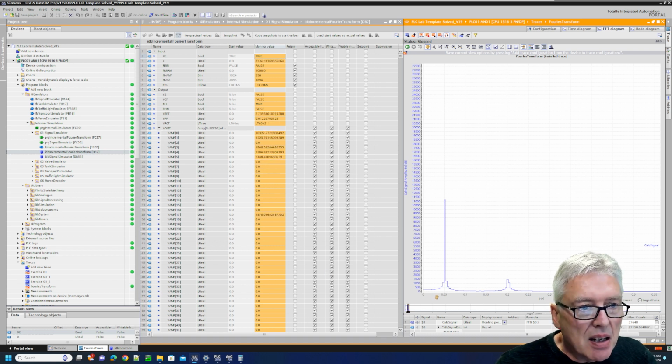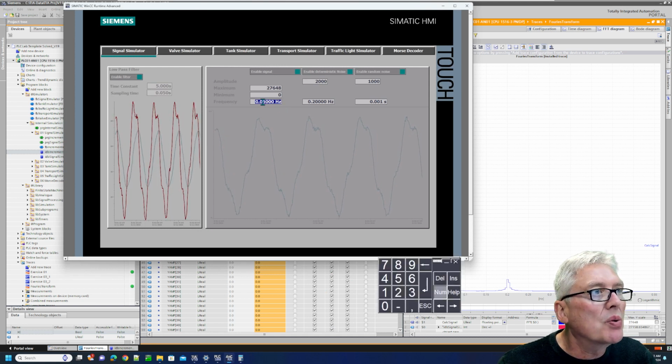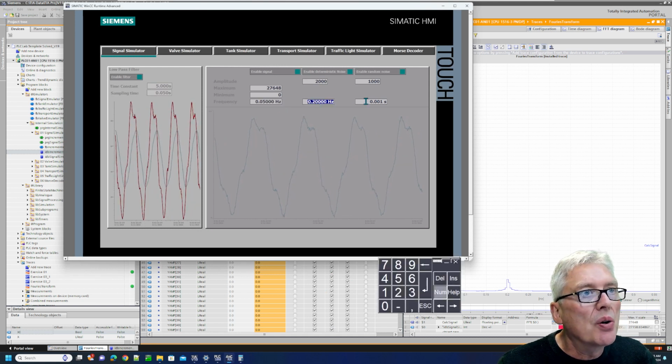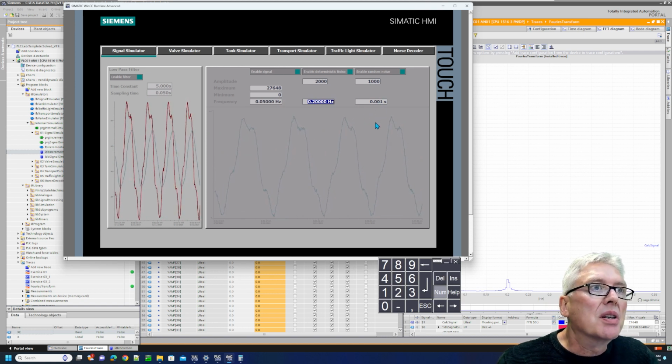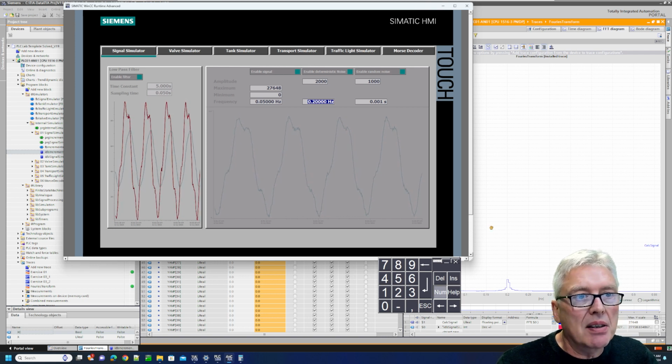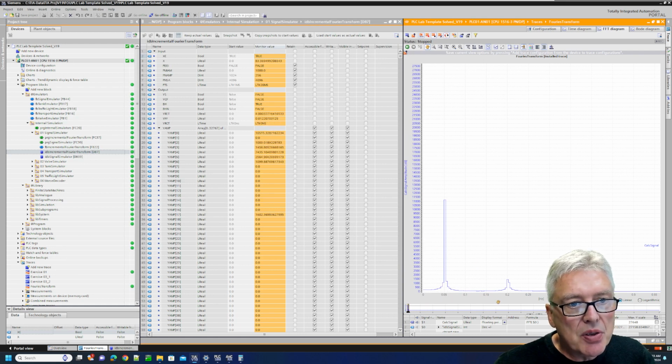If we look at the signal we have here, that's where we set up the signal. We have 0.05 hertz here and 0.2 hertz, and then this random noise is just updated every 10 milliseconds or something like that. Here we get 0.05, a strong amplitude, and here is 0.2. I have a signal, and then there is some noise all the way along, and that's random noise. It should have pretty much the same amplitude all over the spectrum. So that is the function.